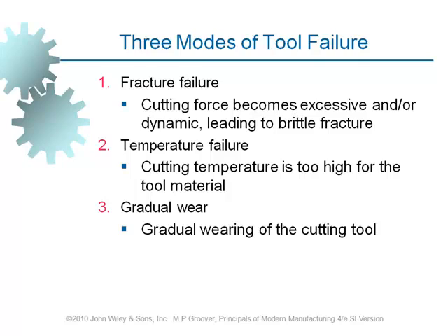By doing this, we can increase the tool life of the cutting tool and also prevent fracture failure. The other possibility would be to make use of a different geometry of the cutting tool, which is stronger, so that it doesn't fail.